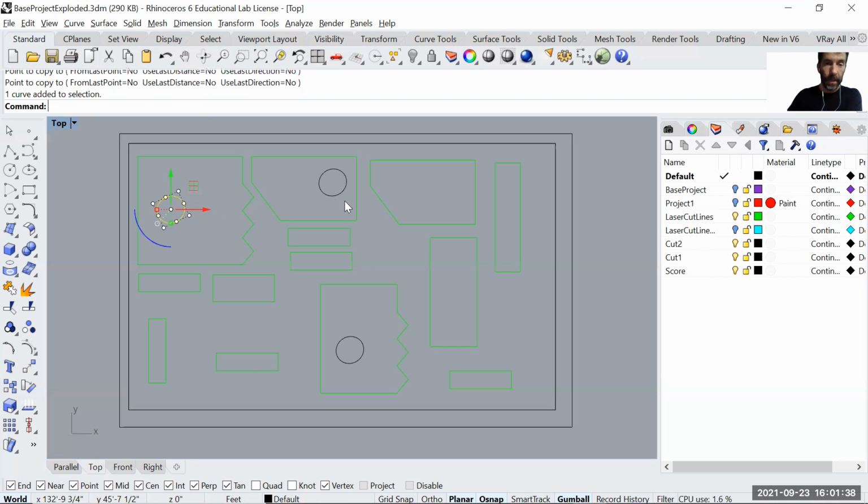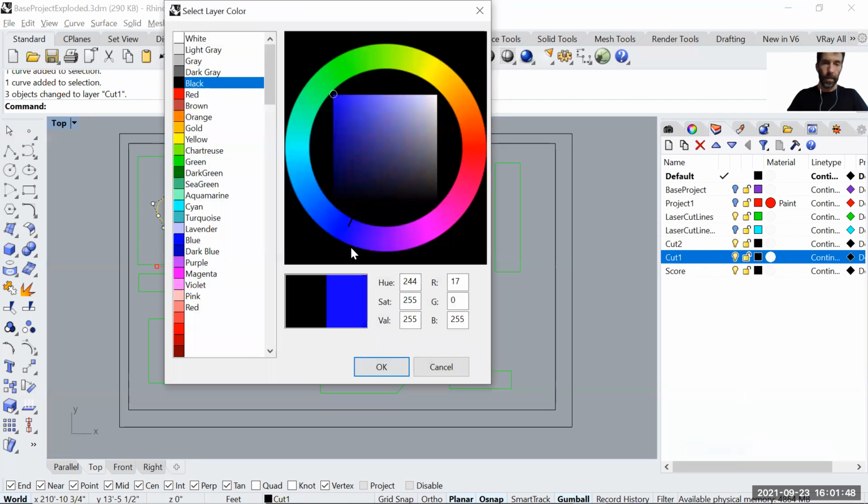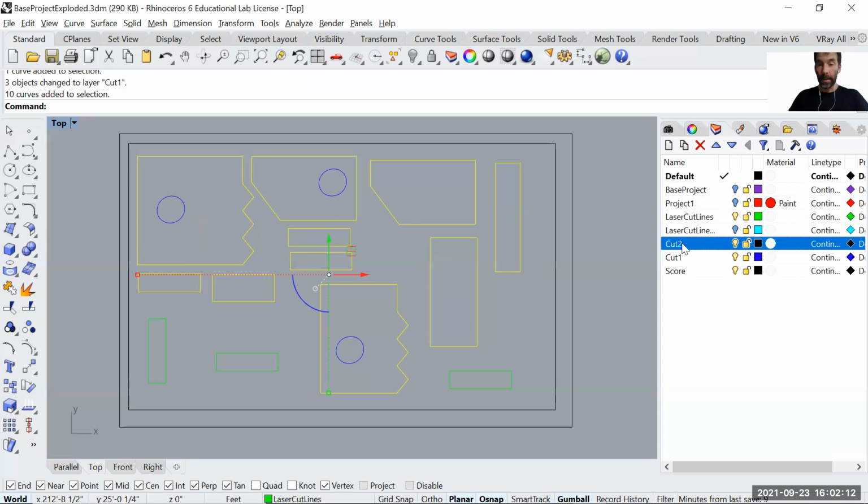You will do every inner cut. You need to bring them into cut 1. And again, the colors and the layers depend on the laser cutting manager. But you want to create those openings and cut them first. So the laser comes and cuts this, zoom, zoom, zoom, and then the big piece. We don't care if that one is loose because it doesn't matter, but we do care that the big one is not loose. Then all of the green guys are going to be in cut 2.